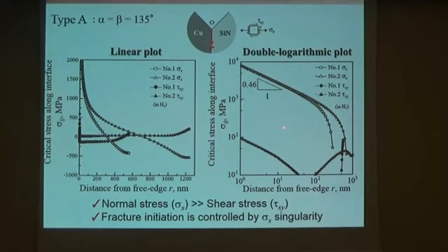The shear stress component is much lower than the normal stress component, and when comparing specimens number 1 and number 2, shear stresses are completely different. But the nearest normal stress shows very good agreement, and they are synced to one simple relation.